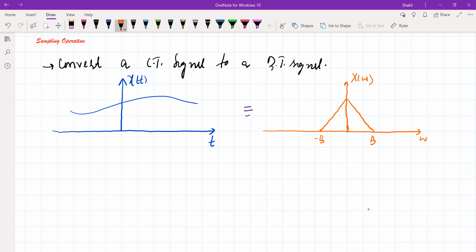Now before I proceed, remember that to compute the spectrum of any signal, we only consider positive frequencies. We never consider negative frequencies. The negative spectrum is drawn only for mathematical convenience. It has no other purpose in signal processing. To make the mathematics valid, we draw the negative frequency spectrum also. Otherwise, it has no part in computing the spectrum of a signal.